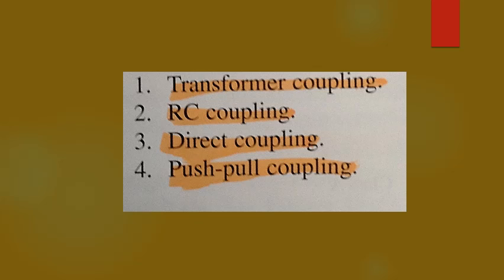(18.6) Coupling amplifiers. Transistor stages can be connected in series to produce the desired amplification. Connecting these stages in series is called cascading. The key challenge of cascading is matching the high impedance outputs of one transistor to the low input impedance of the next transistor without severe loss in gain.